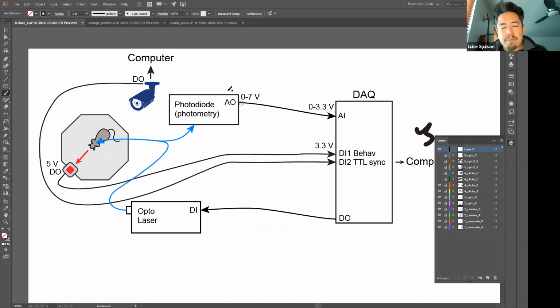Okay, one thing we could imagine doing would be to set this thing up so that we can configure it so that it never goes above 3.3 volts. I'd recommend against that for a couple of reasons. One is that we're not using the full output range of this, so our signal's not going to be as good. The other thing is that in a lot of situations, you can actually damage this analog input if you give it more than 3.3 volts. So what you want is some sort of system where you can change that.